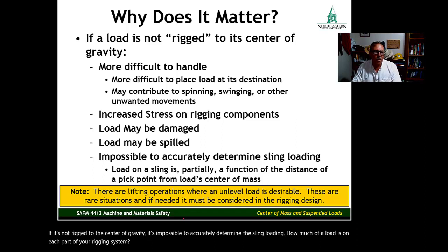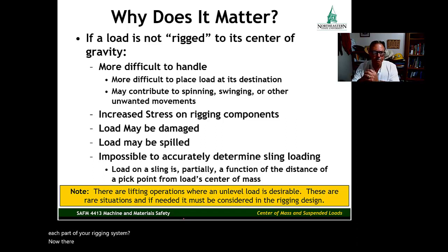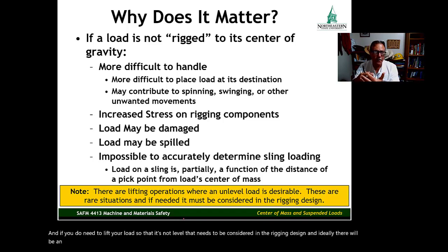Now, there are lifting operations where an unlevel configuration or an unlevel position may be desirable. These are rare situations, and if you do need to lift your load so that it's not level, that needs to be considered in the rigging design. And ideally there will be an engineer qualified in rigging design involved in this type of load where we want to purposefully rig it so it sits off level.